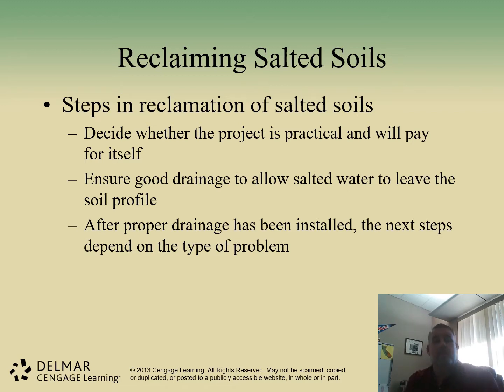So what do you do to fix these salted soils? It comes down to a few things, and you first want to make sure that it's practical to do this work. Is it financially viable? Is there enough good drainage to give the salt water a place to go?